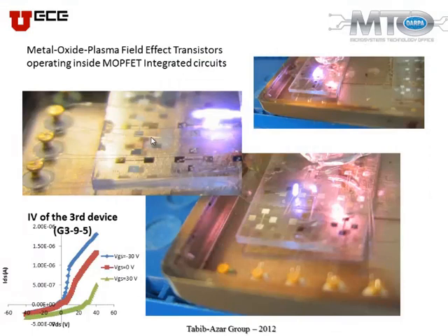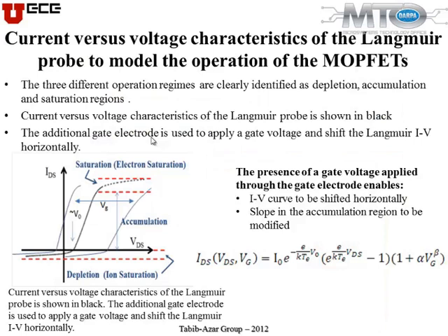So the kind of IDS versus VDS as a function of gate voltage that you get, our typical ones are shown in here. Our objective is to make these as sharp as possible in transition, and also separate them as much as possible. So you can define transconductance similar to what you have in FETs for these devices, and these are actual devices under operation shown in there.